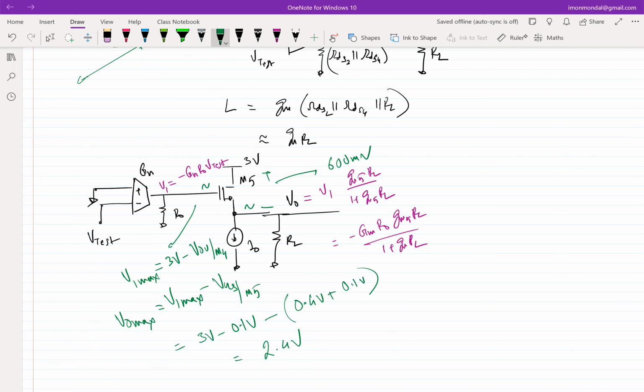Even in ES201, you have used 741 op amps. The output stage of the 741 op amp is a source follower, right? A slightly different source follower, but a source follower nonetheless. But your 741 works at very high supplies. It can go to plus minus 10 volts, right? So it's not too much of a problem. But when you use custom design with low voltage supplies, this is something that you see less and less of.